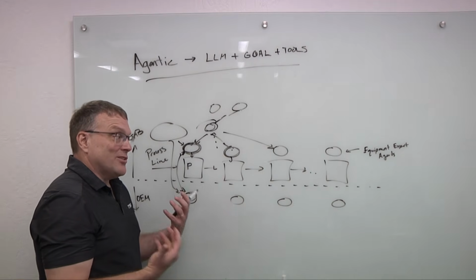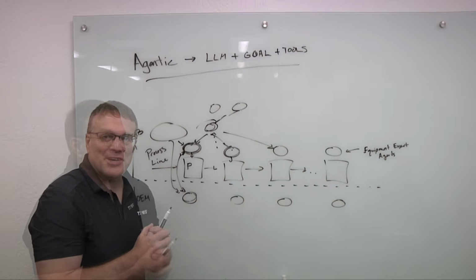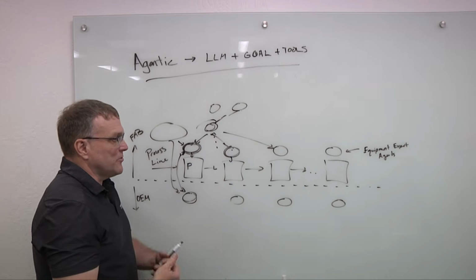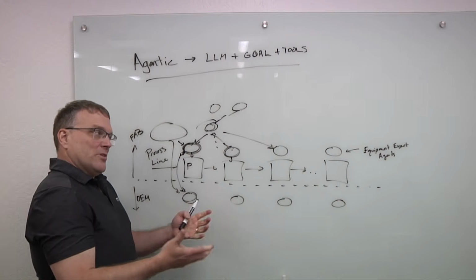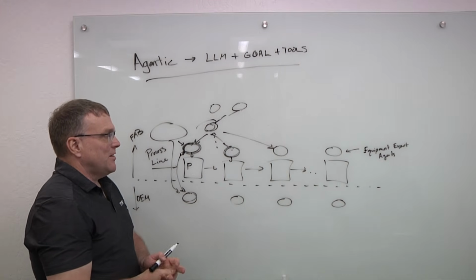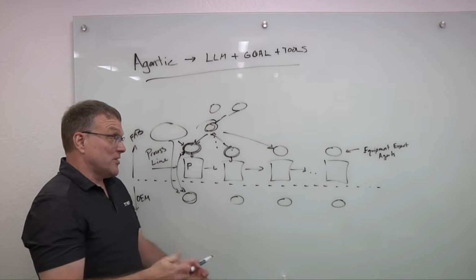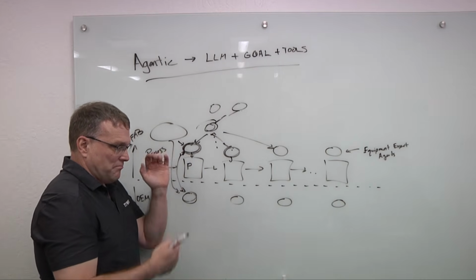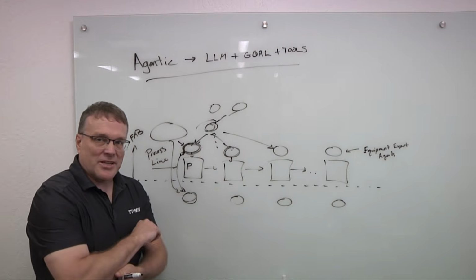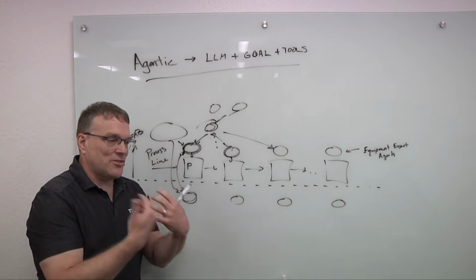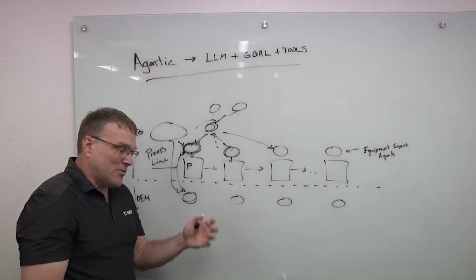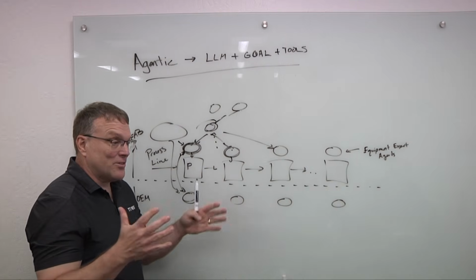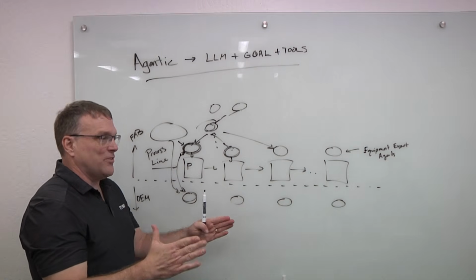We know that fabs are conservative, but I think we will see some people leading the way and driving the research on how to do this. What does it look like? In some ways, not so different from the things we do today. When we develop advanced process control, we are asking an algorithm to take control of our system. How do we convince ourselves that it's trustworthy? First of all, we create bounds. We say, you're not allowed to go outside these bounds, so we limit the damage, at least in some way.